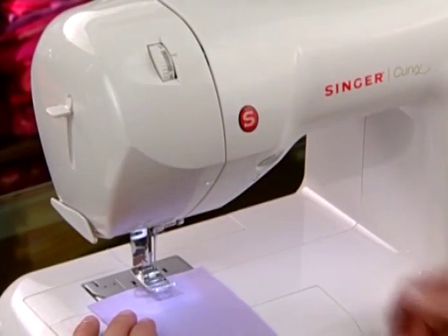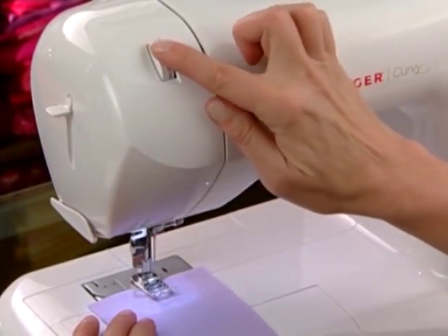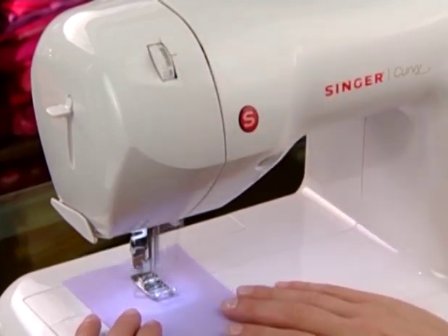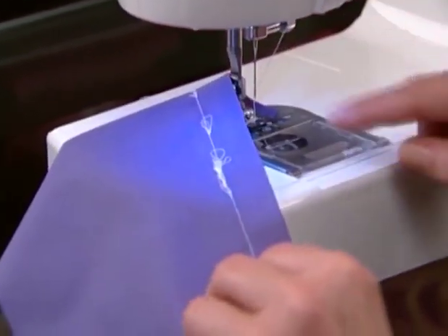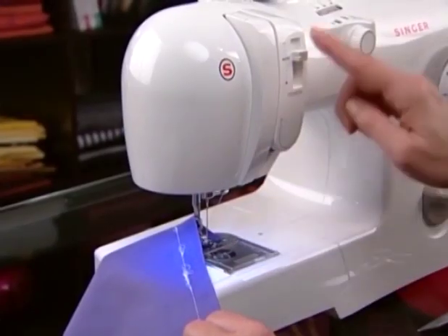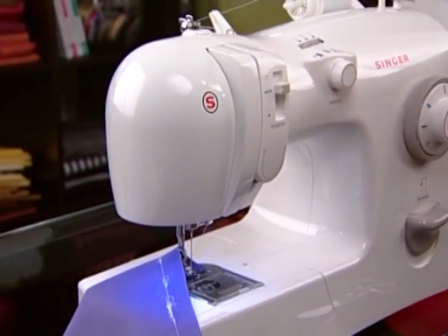Make all tension control adjustments with the presser foot in the down position. If you notice that there is a lot of thread accumulating on the bottom side of the fabric, this is an indication that the machine has not been correctly threaded. For more information about this, go to the Maintenance and Troubleshooting section of this program.